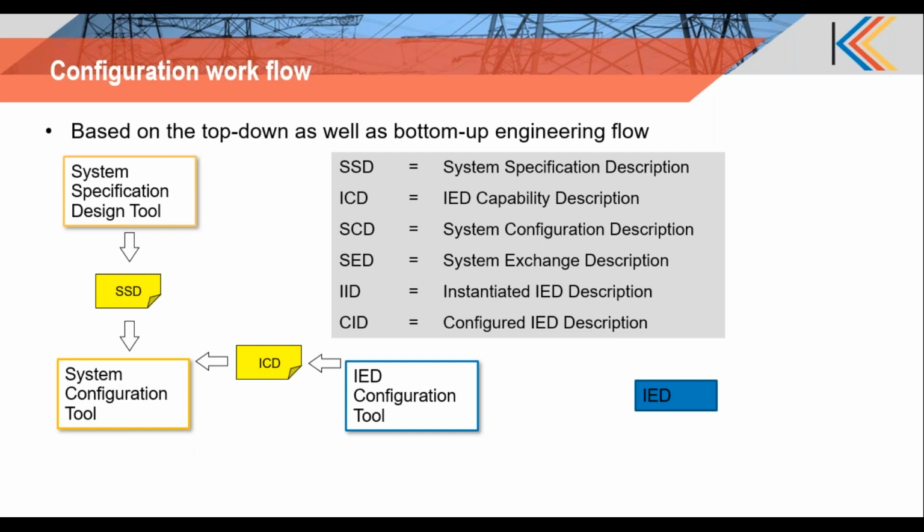Instead, all of the data model will be mentioned as data templates, and it is the responsibility of the system configuration tool to instantiate those templates and give them appropriate names which represent the actual IEDs that are planned to be deployed in that configuration. So the system configuration tool essentially ingests the SSD file and the ICD file.